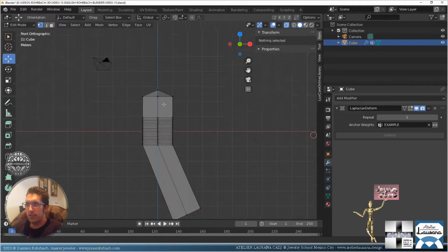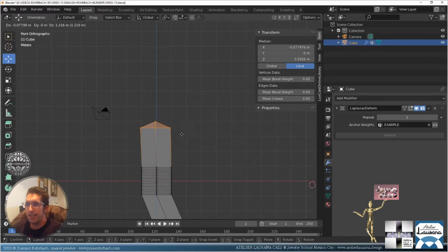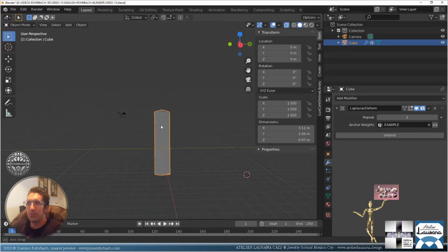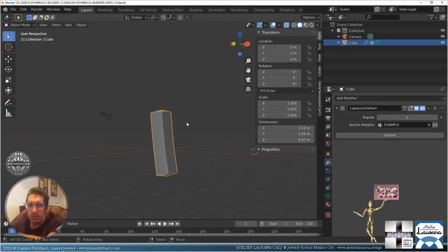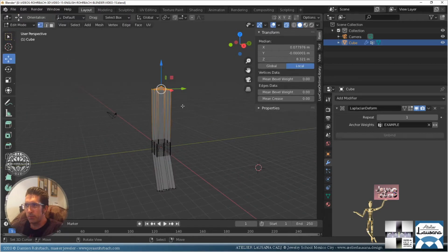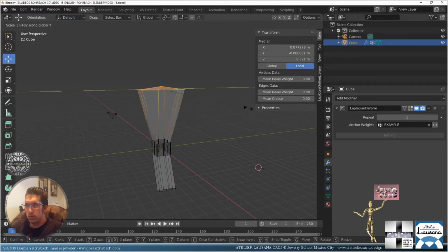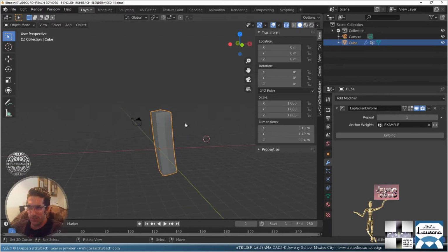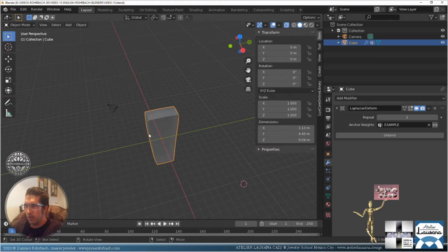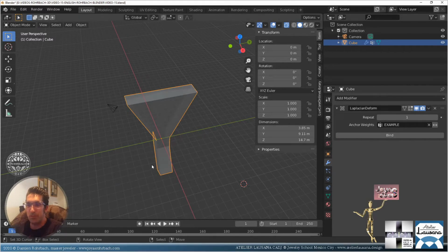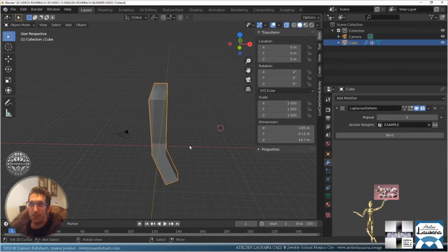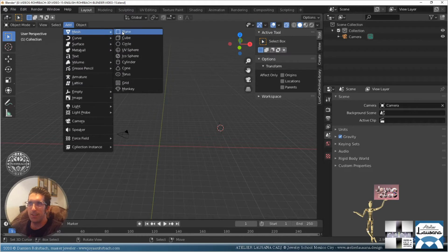And the interesting part is that I need to make less modification to the mesh, to the anchor vertices, to get the deform result through the Laplacian deform modifier. Let's do this. So again, for prong designs, this is also pretty good. But what I don't like with this modifier is, let's say I'm going to unbind it, and my original mesh is totally destroyed, and that's not cool, because now I need to erase it and make a new cube.